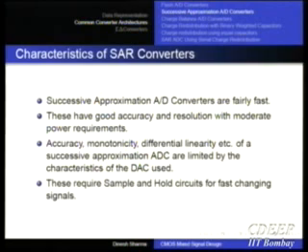The value on the output of the D2A is increasing monotonically. It does decrease sometimes, but the point is that the bits are always being set. You may reset the previous bit, but then the bit is being set, and because of that the value doesn't change that dramatically. So you are not that much slew rate limited. That can become a problem, but you are not that much slew rate limited.